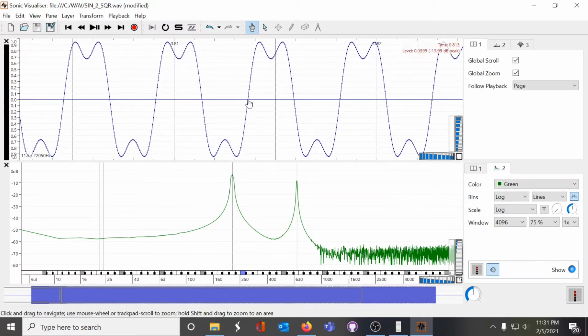Originally, this signal went up and then came back down, but because we're adding the third harmonic, the valley of the third harmonic is suppressing the peak of that sine wave. On the other side, the third harmonic has a peak at the valley of the fundamental. So it ends up increasing the amplitude at this particular point.